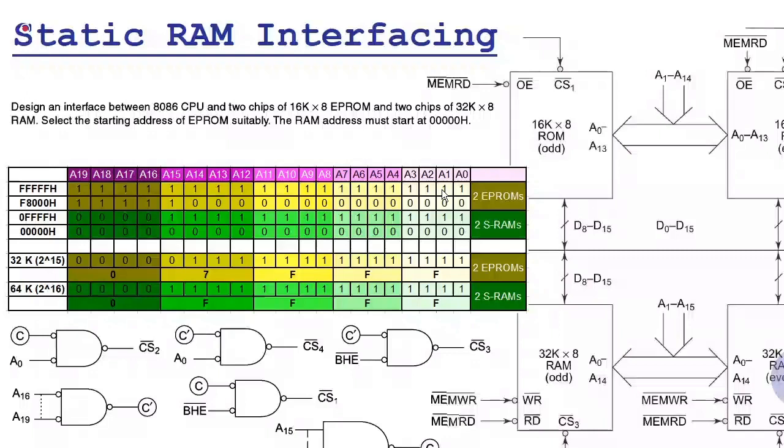Because in 8086 we know that we have the memory chips which are organized as odd and even memory banks, on the account that we want to write one word of data in one machine cycle. That means 16-bit data should be written in one machine cycle. Every location in memory is of 8 bits or 1 byte, whether it is ROM or RAM.